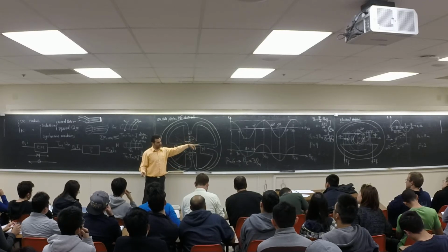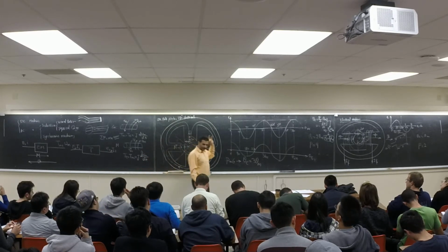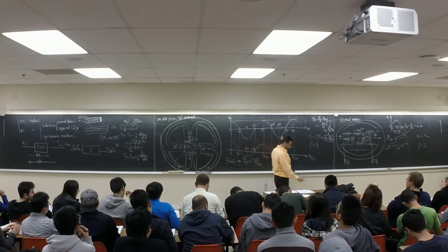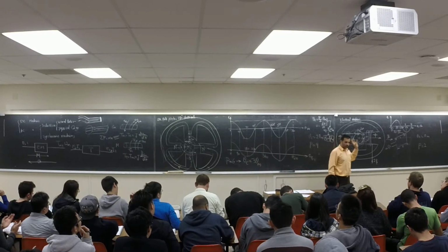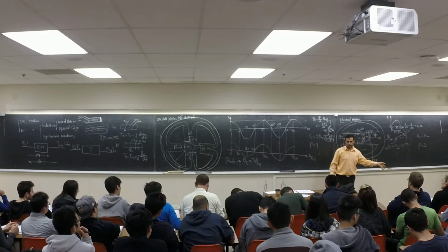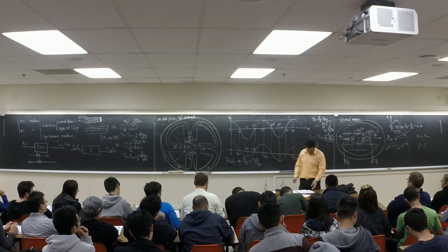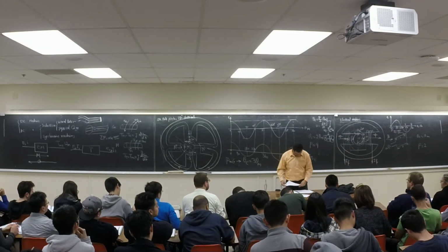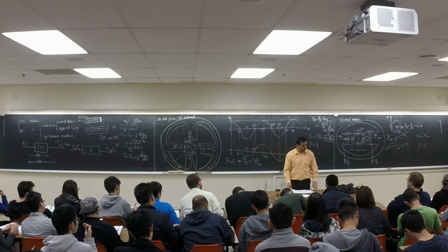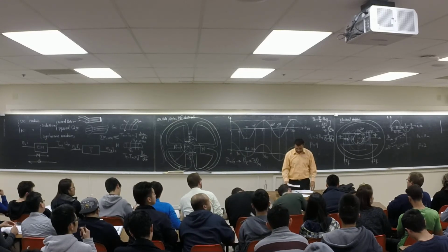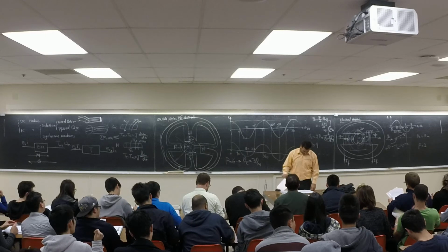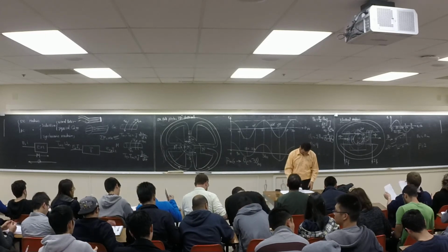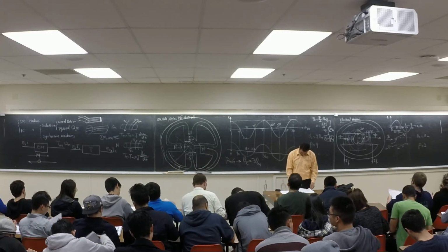So again, the same equation with the P: you can say the electrical pole pitch is equal to P over 2 times the mechanical pole pitch. So this is the definition of pole pitch, and I wish I had a little bit more time, but let's stop.